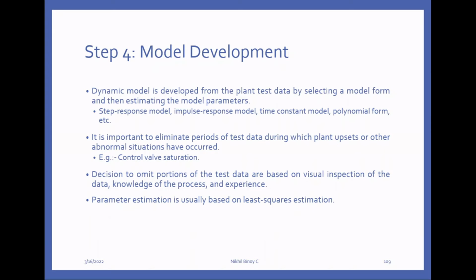Here we are not doing any parameter estimation or adaptive, we are not designing any adaptive controller. But for model prediction, first we have to know the model. To identify the model, either we can use the transfer function derivation process or we can use parameter estimation. If you are using parameter estimation, least square estimation is normally used.